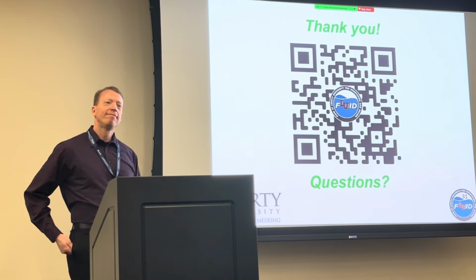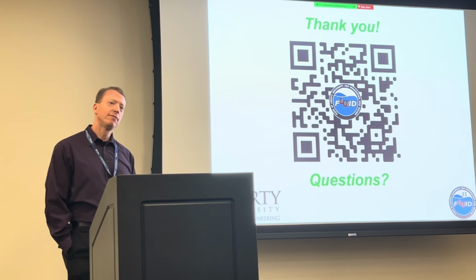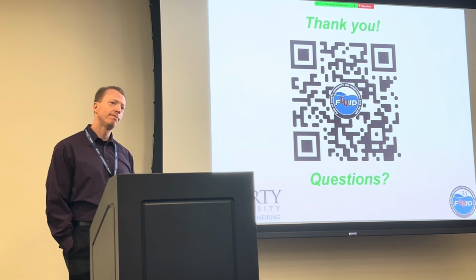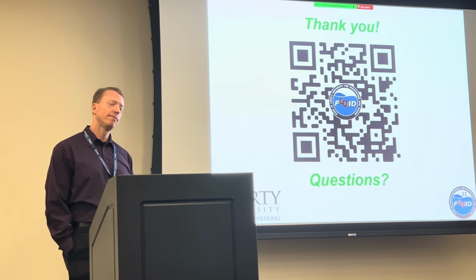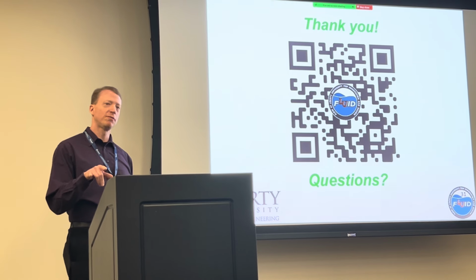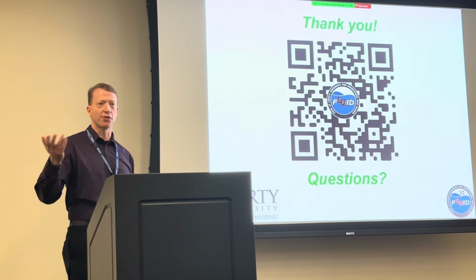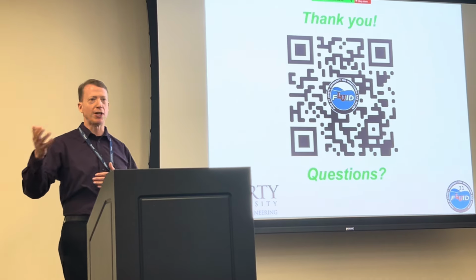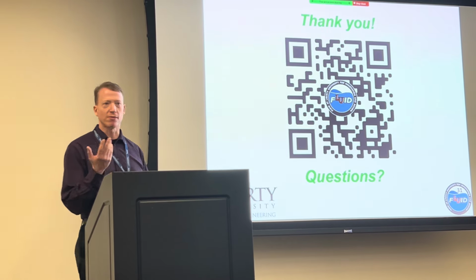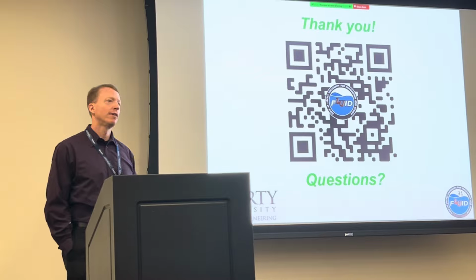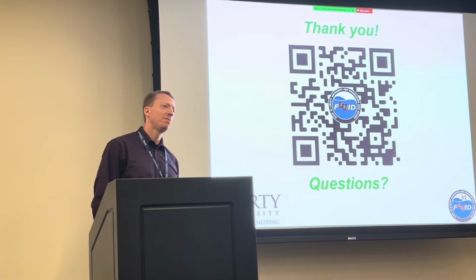Yes, Gabriel. Why do you non-dimensionalize the data and results? So for example, when you're giving length, you put it in terms of the diameter. So that it's more universally applicable, so other people might be able to repeat the research, and because that would apply to nozzles that are on the centimeters scale here or meters somewhere else for a given Reynolds number, Mach number, whatever. Thank you. Great. Thank you for very nice work.